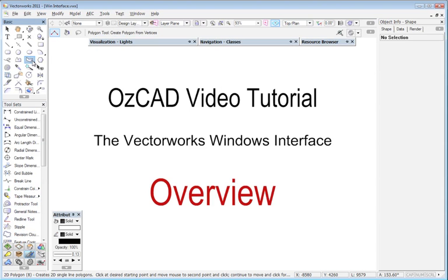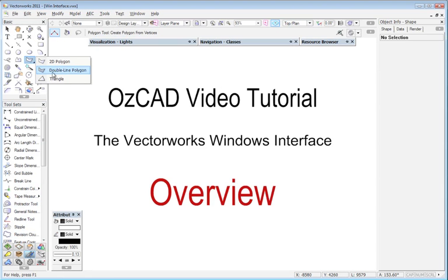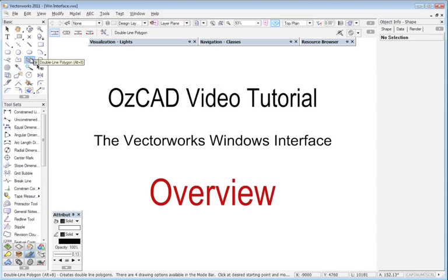If we hold the mouse down then eventually a little menu will fly out and we're able to choose a different tool. You're also able to access that very quickly by right clicking and then going to choose the other tool that might be hidden, and that tool then becomes the active tool and the other one becomes hidden. So there's not that many tools that have other ones below, but there are some, and you need to look out for that little arrow if you find that you think a tool should be in a particular position and it's not there.